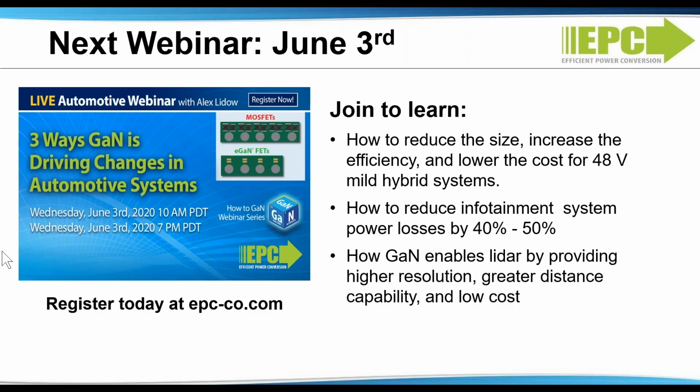In the case of the multi-level converter, we use one driver for the 2 lower FETs and then one high side only driver for the 2 upper FETs. And we have a how-to app note on that, by the way. So if you want any details, you can go to our website and find the how-to app note for the multi-level converter.